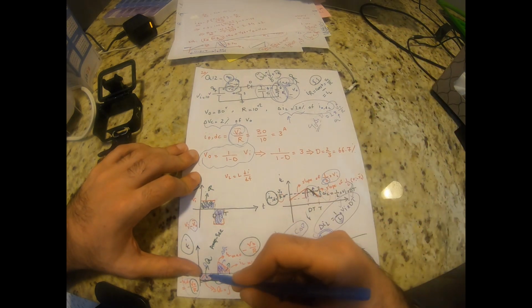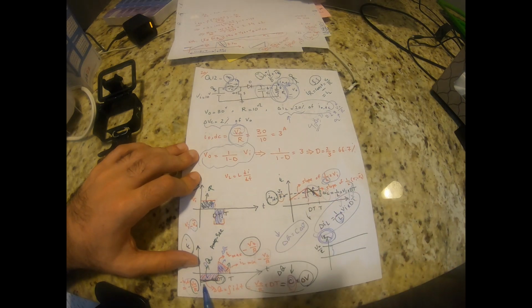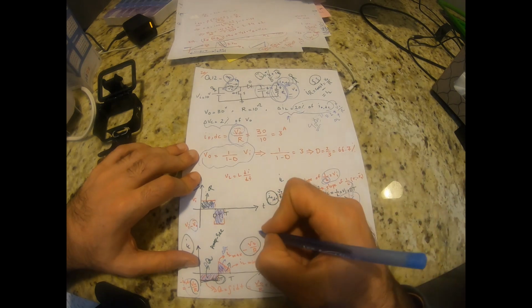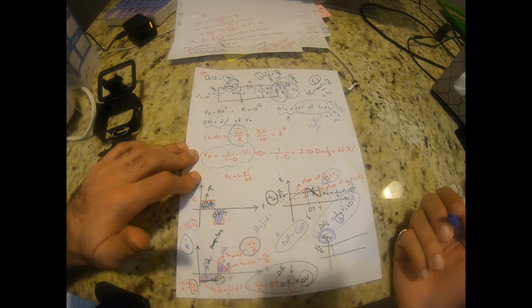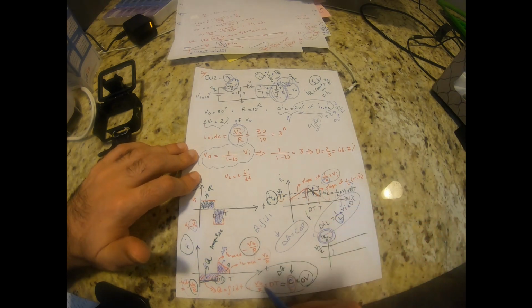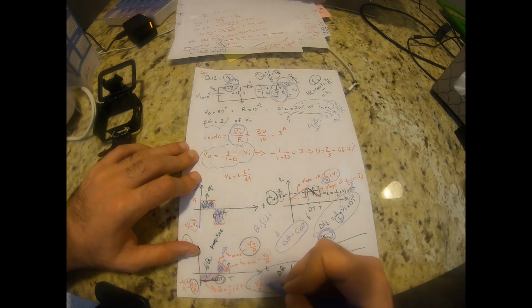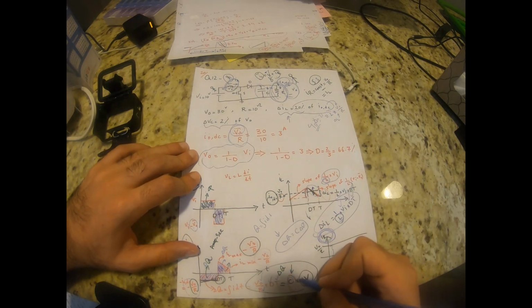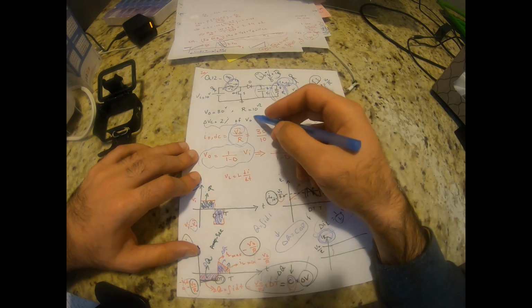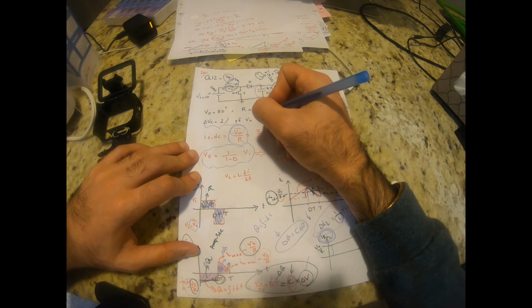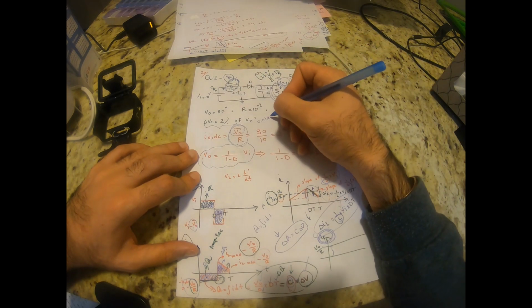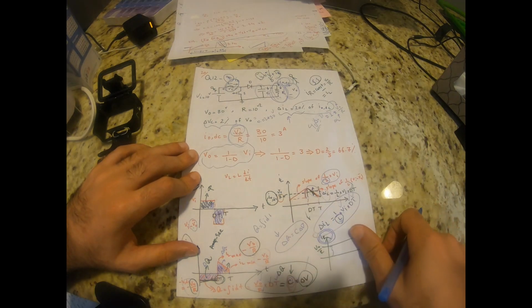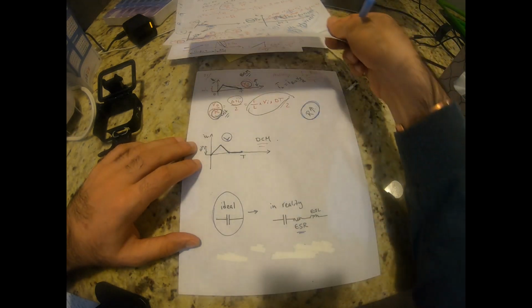At the same time, this delta Q is going to be VO over R times dt. It's going to be this area because Q is the integral of I dt, right? Amp-second is the unit for charge. So if you make these two equal, you have VO, you have R, you have D, you have T, you have delta V, which is given as 2% of VO, so it's going to be 0.02 times VO, whatever VO is, 30 volts. So you can calculate what the value of C is.